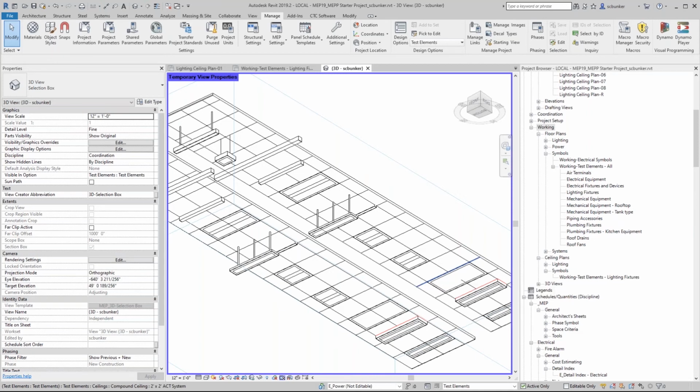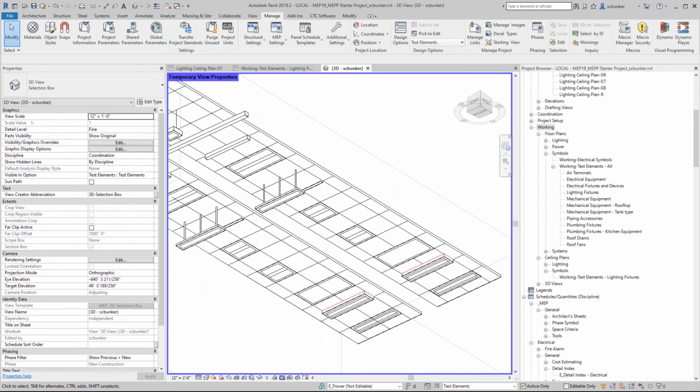If you've worked in Revit, when you download manufacturer families, you always have problems getting them to show up in schedules properly because they don't have your parameters in them, and they just don't always work seamlessly. In fact, they usually don't work seamlessly. So instead of doing that, you can just configure these to be the general shape and size that you need, and it will represent the manufacturer families perfectly well.